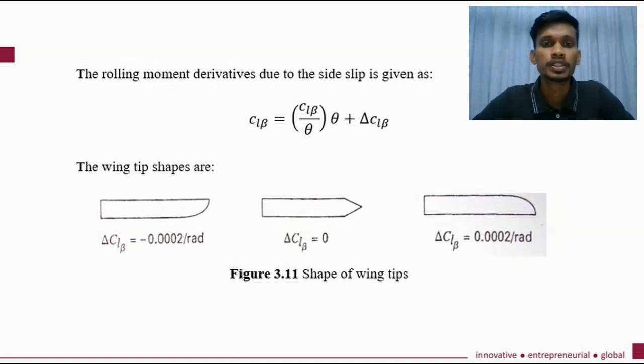The principal surface contributing to the lateral stability of an aircraft is the wing. The effect of geometric dihedral is a powerful contribution to lateral stability. Dihedral angle is the angle between the plane of each wing and the horizontal when the aircraft is level. Wing position also greatly affects the lateral static stability. A high wing location gives a stable contribution.